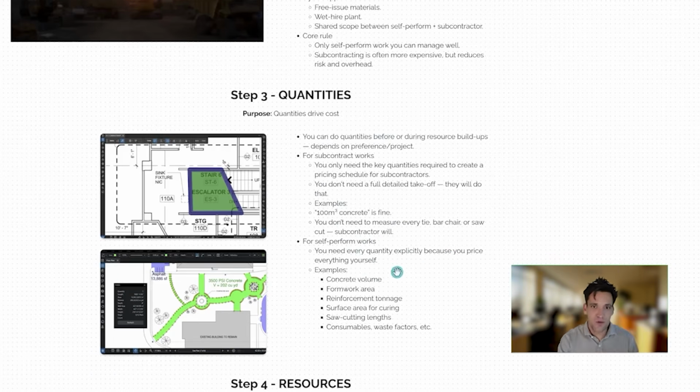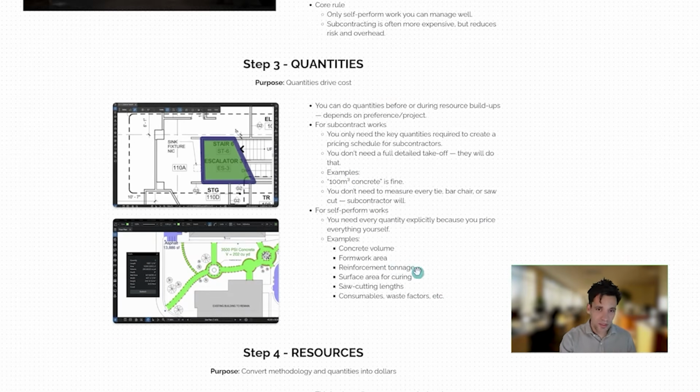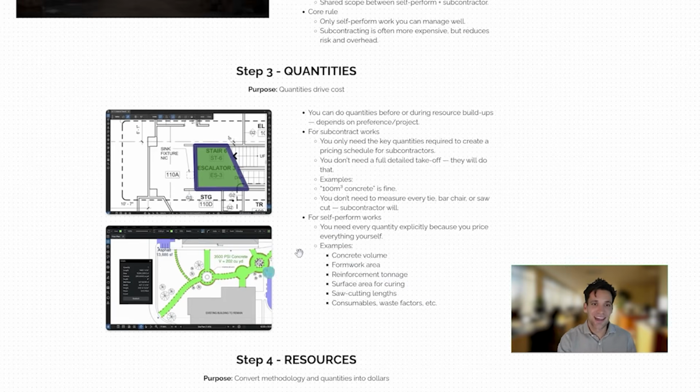For self-perform works, you're going to be responsible for measuring every single quantity in detail. For example, the concrete volume, formwork area, the tons of reinforcement, the surface area for curing, any saw cutting lengths, consumables, waste factors, and so on. Every single quantity in detail needs to be measured.